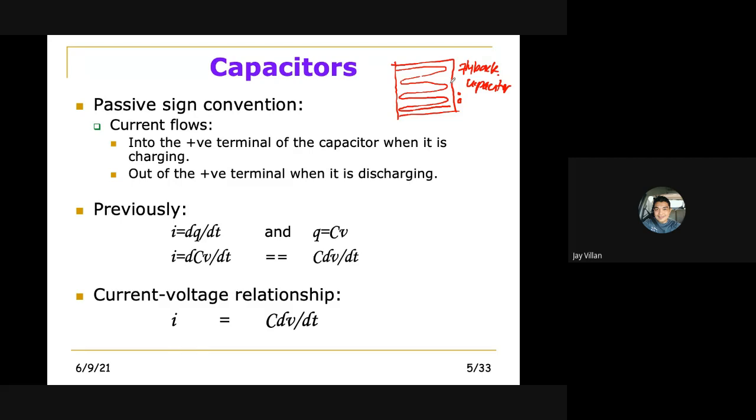TV monitors of computers before: do not open unless you are a certified technician. Do not open this or touch this unless you're a certified technician, because the energy stored there is very large, and if you touch that and you are connected directly to the ground, or to the table, which is connected to the ground, then you will feel a large amount of energy by electrocution.